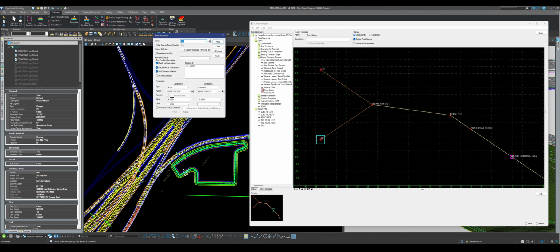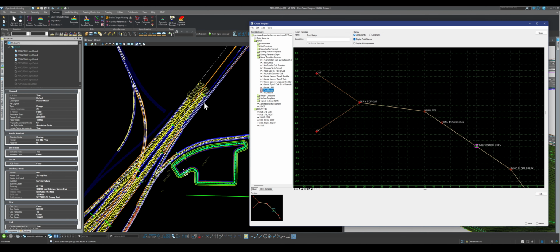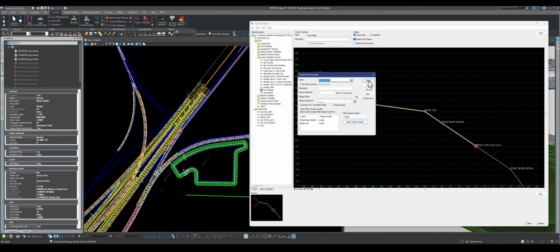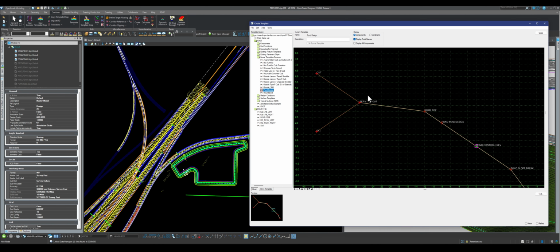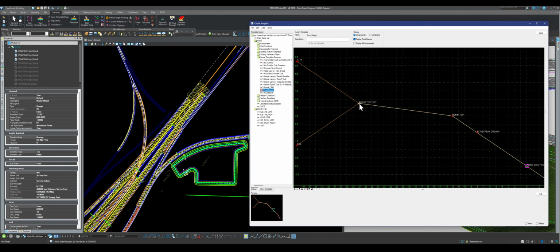So they have it as 25, right? That's 25%. These are the cut and fill. So you can actually come here and double click on them and make your template like them. Meaning double click on this, see what the name is that they have, which is pond slope. You can name all of them that, and this you see, they call it ditch slope. That's what they actually used. That's what FDOT has to use. And let's look at the points, what they have.